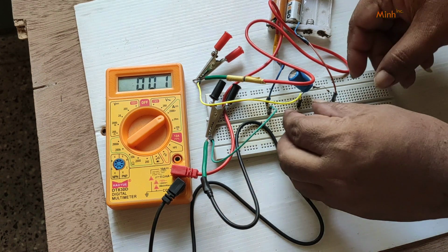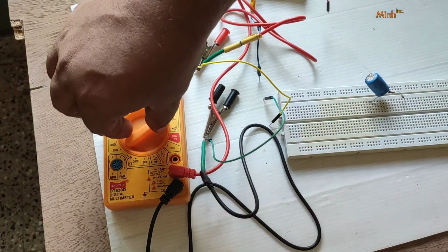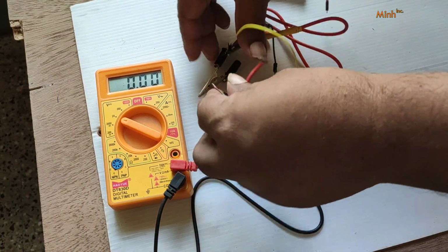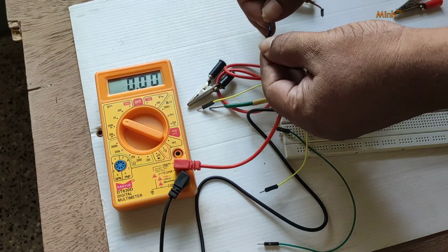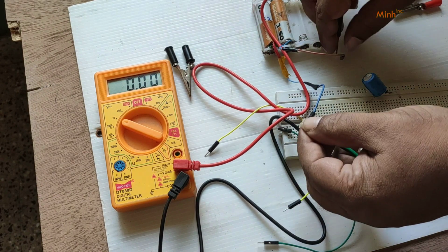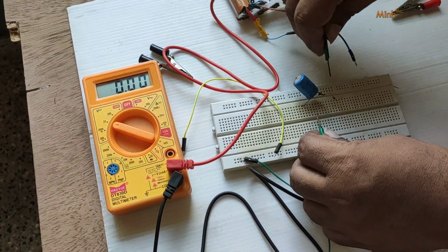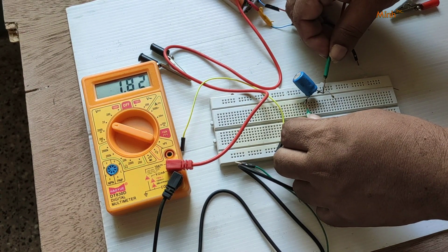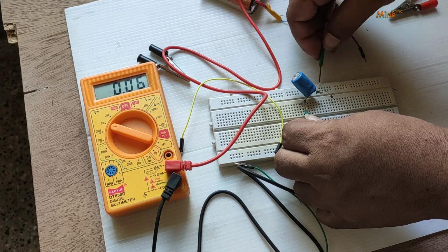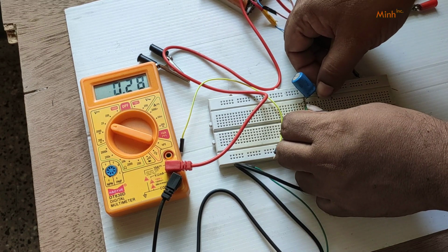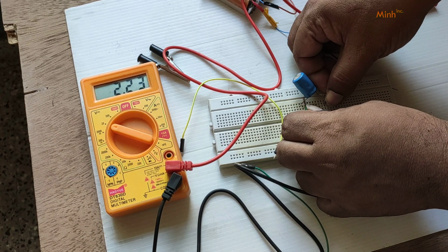Now we'll calculate the voltage across the capacitor. We'll disconnect the capacitor altogether, so now there is nothing in the circuit. We'll measure the voltage across the capacitor. How much did it reach? What is the battery voltage? The battery voltage is 2.56 volt, and we'll measure the capacitor voltage, how much it has reached. Okay, 2.4 it reached. It is decreasing, so it would have reached higher than that. Okay, it is 2.28, so it is decreasing. So the capacitor is getting discharged.